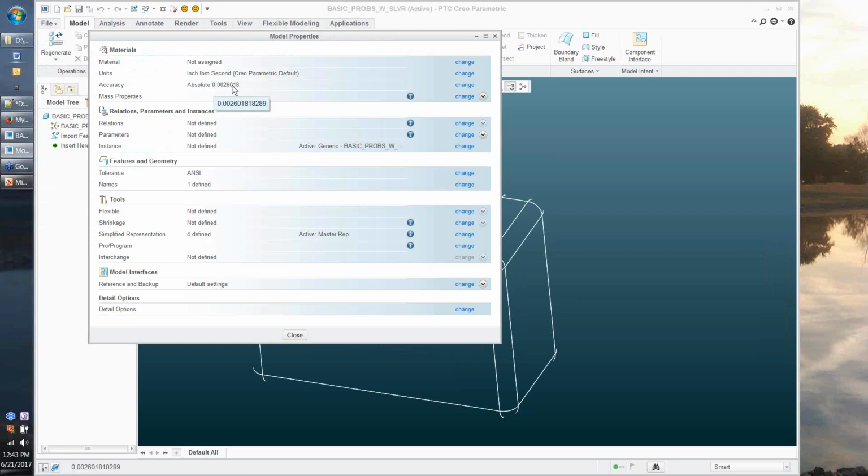And in the context of mold, for me, this number becomes the lowest common denominator. All part files will get matched to that number. End of it. If I start with that number, I know there is never a problem getting all of those files matched out to that number. So that's how I would work to get things recorrected if I found myself in a situation where I had different accuracies. The reference part is your Bible, and the reference part establishes your accuracy for the scope of the tooling for anything that touches or intersects the reference part, in the context of how we would say to do things formally, if you will.